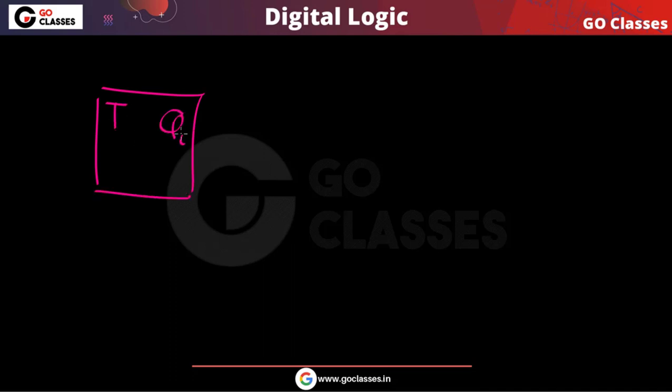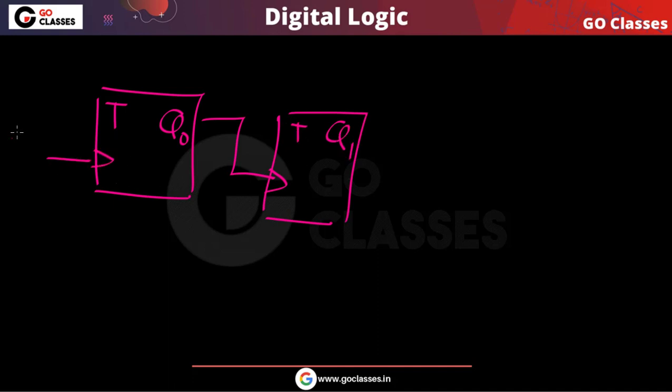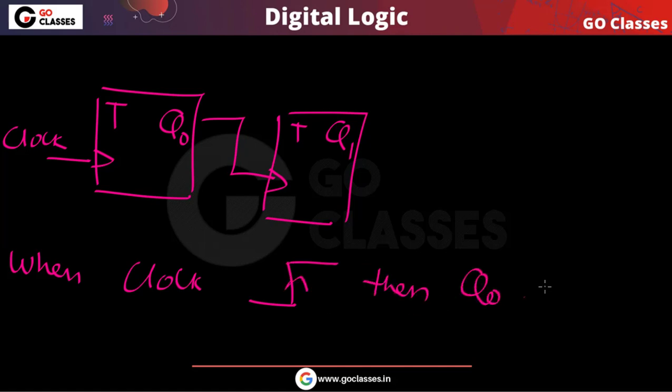You can notice this is your q0, and this is working as the clock for the next flip flop. This is your q1, this is your t. Okay, and this is the clock. Now you can very easily notice that when this clock is going from 0 to 1, then q0 toggles.